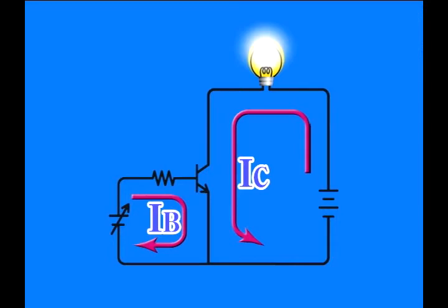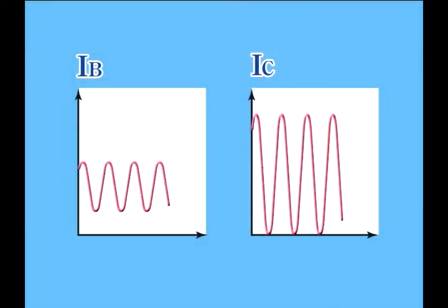When the amount of current IB passed to the base is altered, the flow of current between the collector and emitter also changes. This results in a change to the current IC of the collector. It becomes possible to control the large collector current IC by the small base current IB when the voltage between the collector and emitter is high. This function of the transistor is known as the amplification effect.